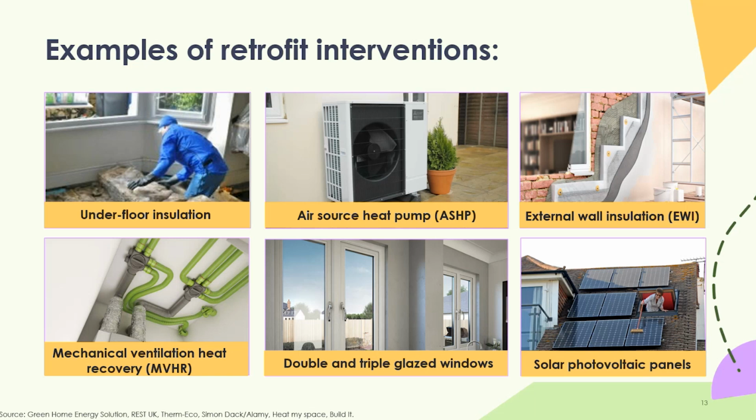There's also a large hot water tank, which you need to find a space for, which in some homes isn't a problem because there might already be a gas boiler with a hot water tank in a property, but not every property that will be retrofitted with an air source heat pump might have that sort of system, particularly if it's a combi boiler in there. And so, it's always worth remembering that, finding space for that large hot water tank on the right there.